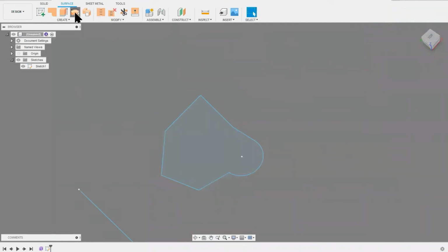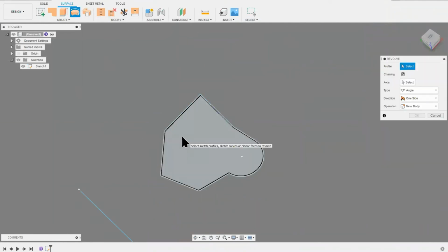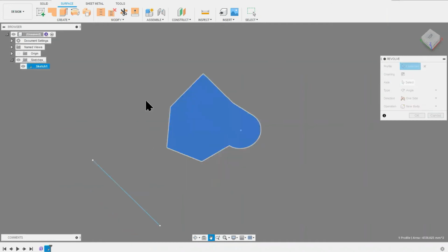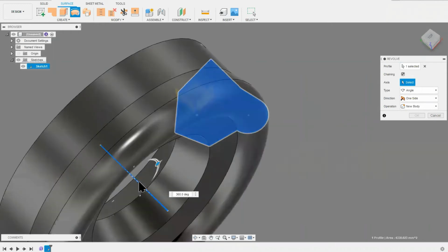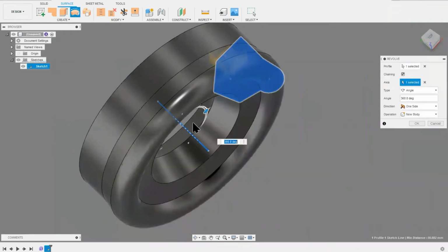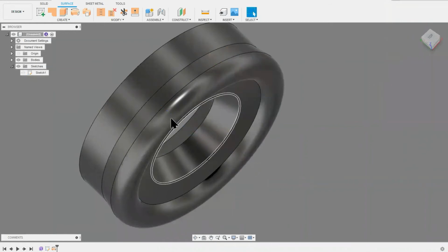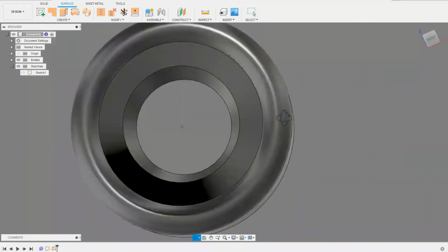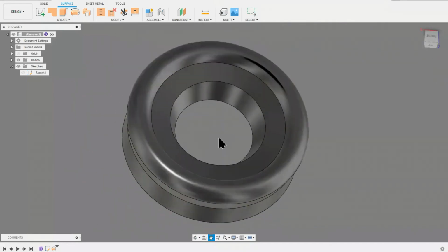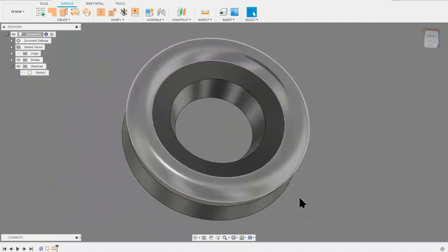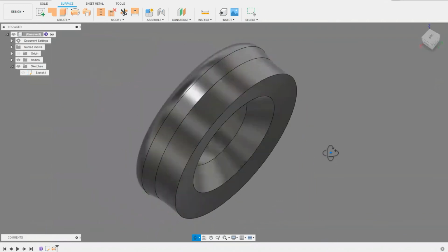This time I'm going to pick a revolve, and we're going to revolve this surface model around this axis. Okay. So what Fusion will do at this point is, again, this is a completely hollow model, so it doesn't have any mass properties as such, but in here we've revolved now to create a surface model based around that particular revolve function.